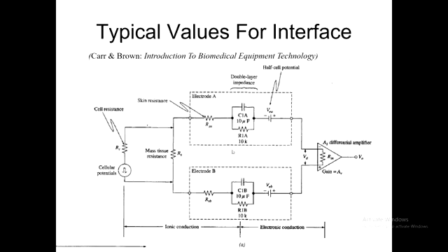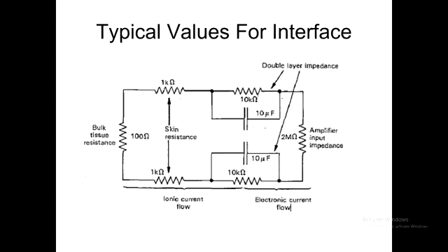Suffice it to say that we can model what goes in from the cell as being a voltage divider driving into some impedance. And as is done here, the driving voltage is considered to be a short circuit. We're just looking at the dead circuit, that is to say with voltage sources short circuited and current sources open circuited.